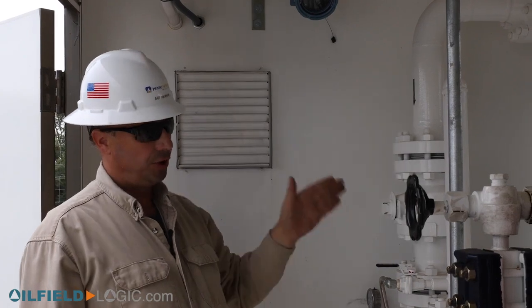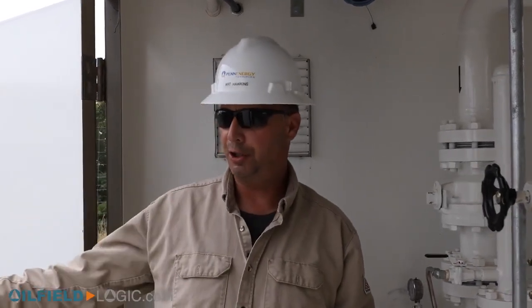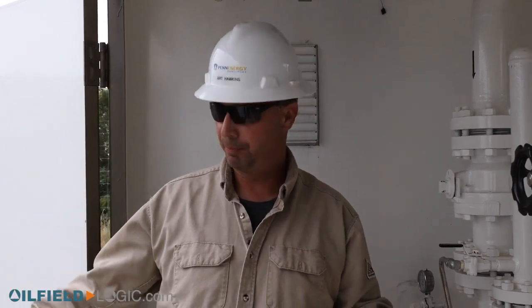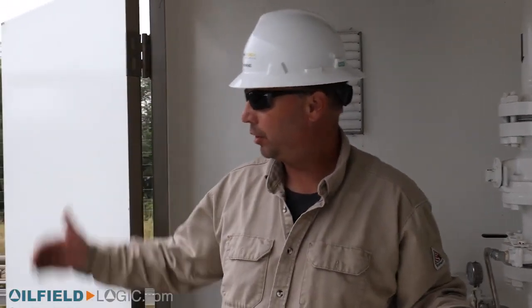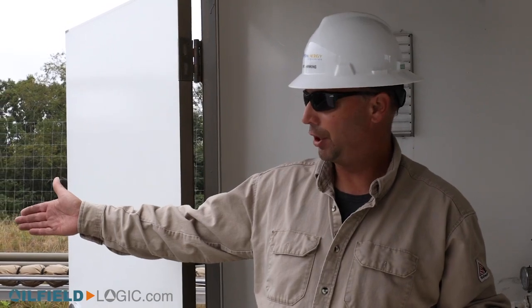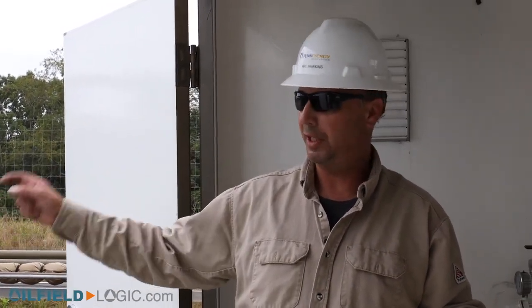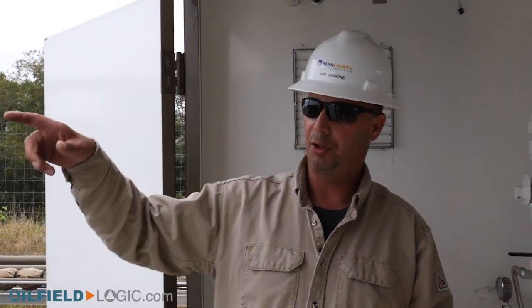It'll also shut all the ignition sources on the pad off. So any other units that are next to this particular production unit will shut off the burners on everything on location. Any other units that are flowing in here will be extinguished. And also we have a combustor on the downstream side, which we'll talk about in a little bit, of our production tank. It'll also shut the pilot off on that device also. Again, we'll get an alarm and we'll come out and address it and see what's going on.